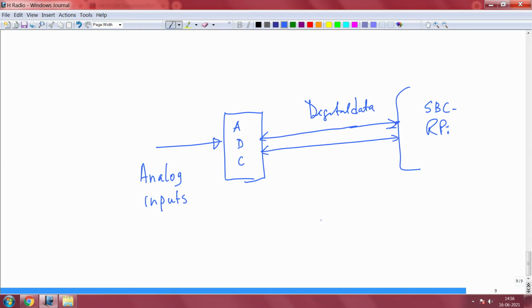If it is 2-wire, these kind of systems typically have what are known as pull up resistors. This is a digital bus, and it has a name called I2C, inter IC communication, that is why it is called I2C.